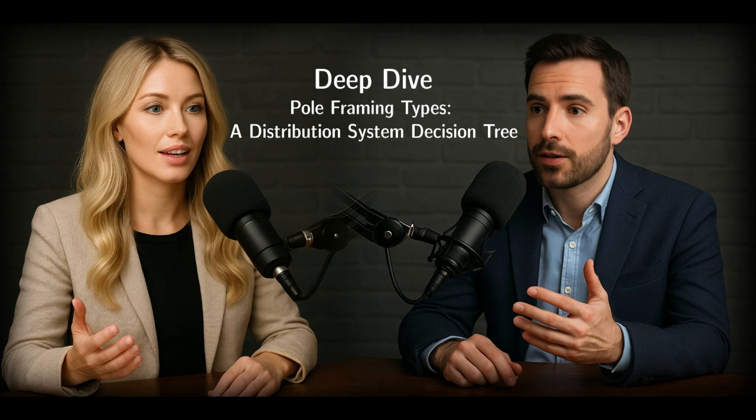Okay, so that guying, that's our unmistakable visual cue then, yeah? It's the pole visibly bracing itself against the conductor's full pull. But what happens if you have conductors terminating from both directions? Or maybe you have a dead end on one side and perhaps a simpler pin-post arrangement on the other, creating significant unbalanced pulls. Okay, good question.